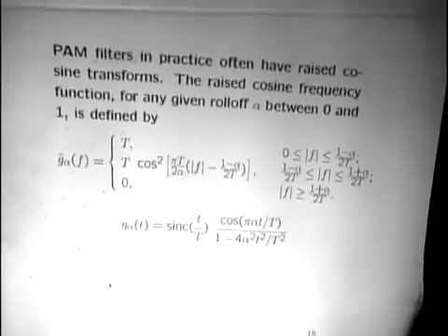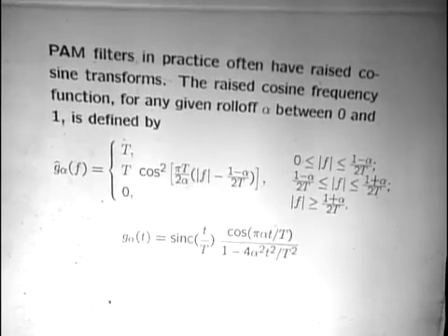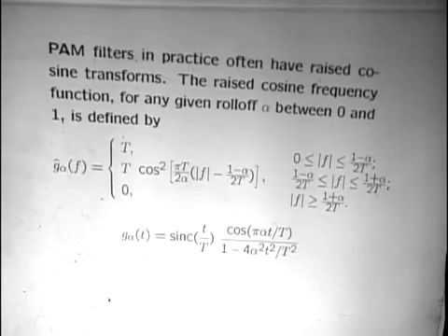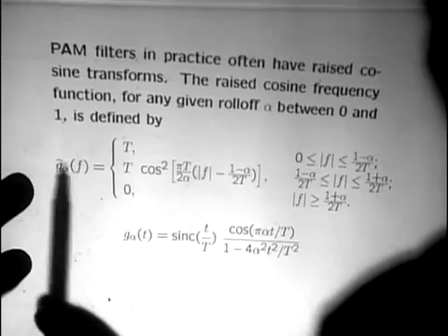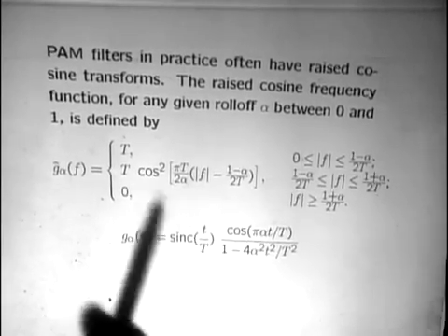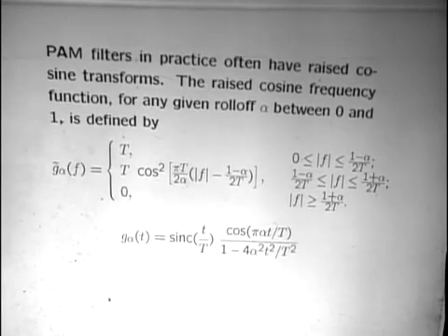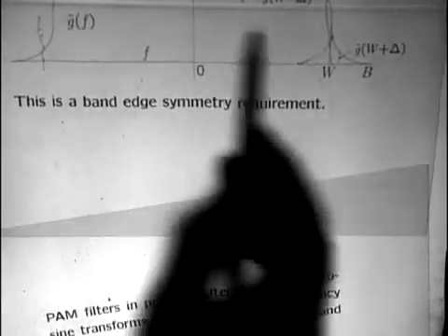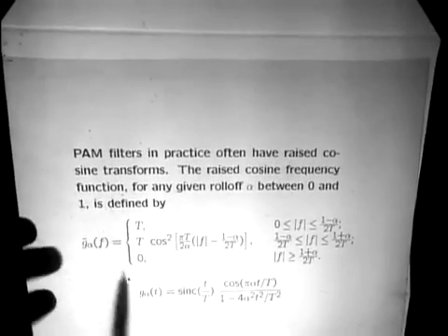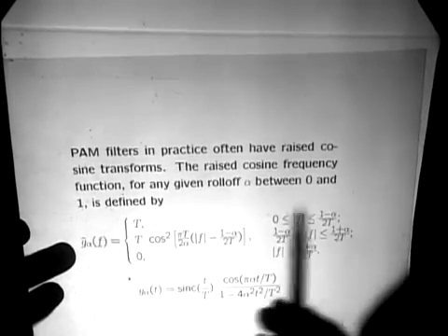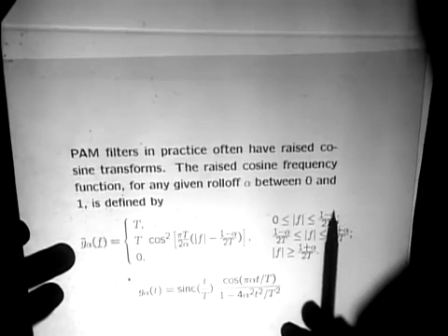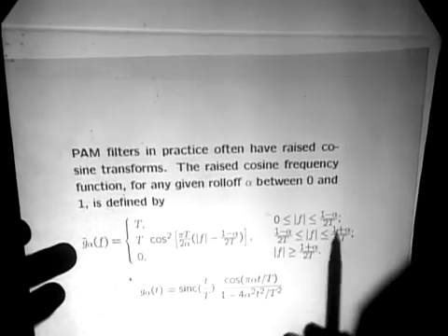And, excuse me for going a little over, but the things people build in practice usually have something called a raised cosine filter, which is this messy expression here for the frequency response, but it really isn't that bad. In fact, it's just what this is, okay? This frequency response is T over most of the frequency interval, up to 1 over 2T.